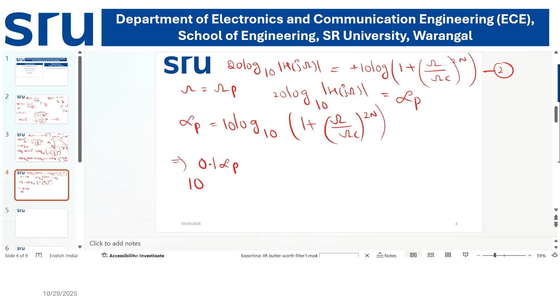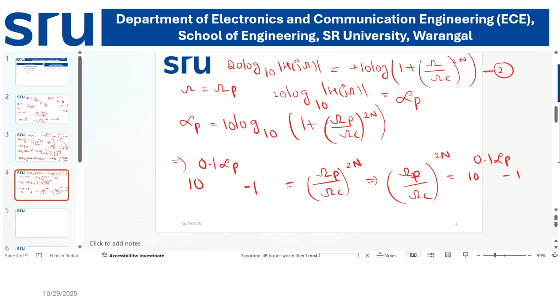And taking the 1 across, minus 1 is equal to (omega by omega c) whole power 2n. What is omega here? Omega is equal to omega p. Therefore omega p by omega c is equal to (10 power 0.1 alpha p minus 1) to the power 1 by 2n. Give it as equation number 3.